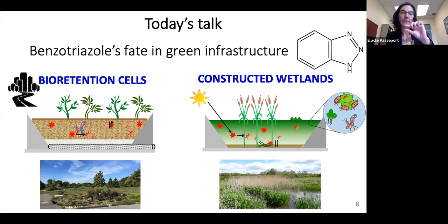They are vegetated with different types of plants or vegetation, and then often there is mulch at the top here. And the main goal of this bioretention cell is really to intercept and reduce the flows of urban stormwater runoff. You can imagine that in a city where you only have or mainly have roads and buildings and parking lots, when it rains, the water has no place to infiltrate. So it just accumulates and creates this runoff.